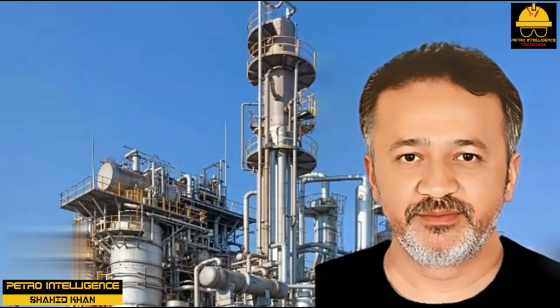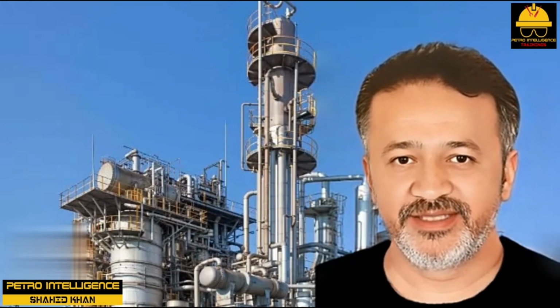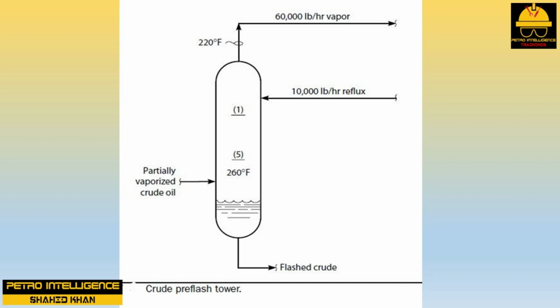Multi-component systems. So far, all our examples have dealt with two-component systems, and many of our towers really just have two components. Also, we have assumed that the reflux rate is large compared to the overhead product rate, and many of our towers do run with a lot of reflux. But we can all think of distillation columns where the top reflux rate is small compared to the overhead product, and the overhead product itself consists of a dozen widely different chemical compounds. This picture represents such a column.